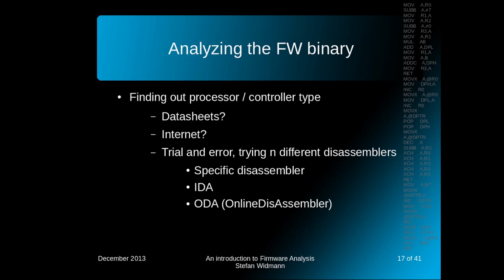Okay. So now you have to be really patient because now it gets to trial and error, trying n different disassemblers. You can use specific disassemblers. They are only built for one architecture. You can use a very good tool, the Interactive Disassembler, IDA. There's a freeware version. I've included a link in the link section of this talk. But the freeware only has a little set of architectures. And if you want the full set, it's getting very expensive.